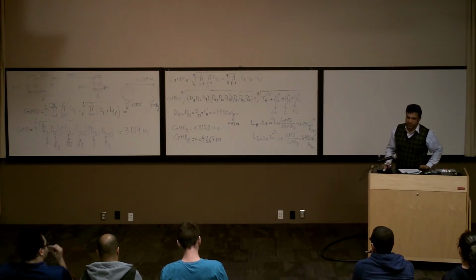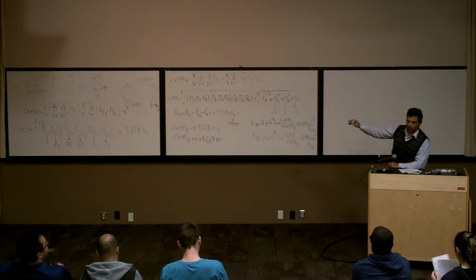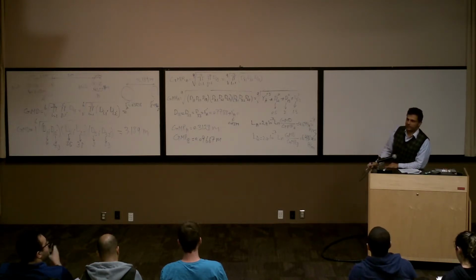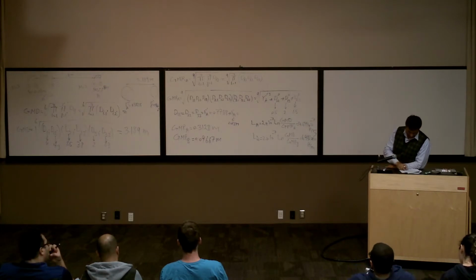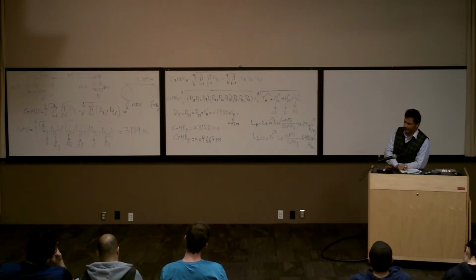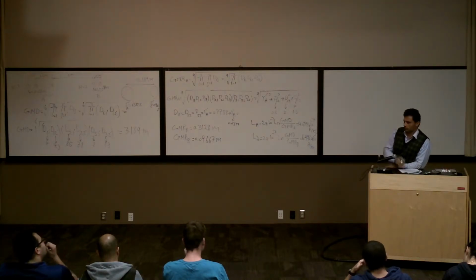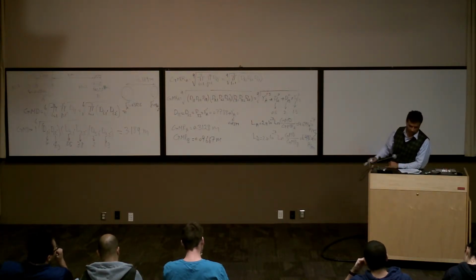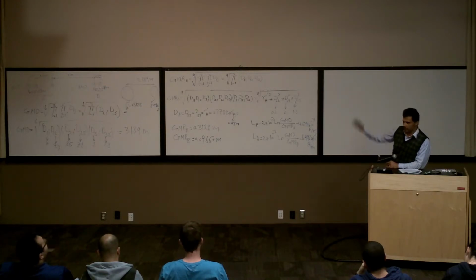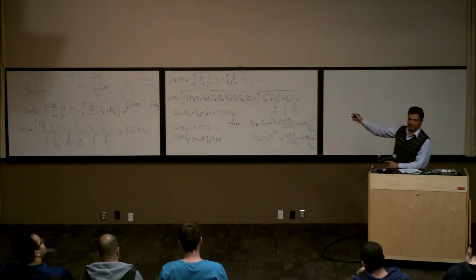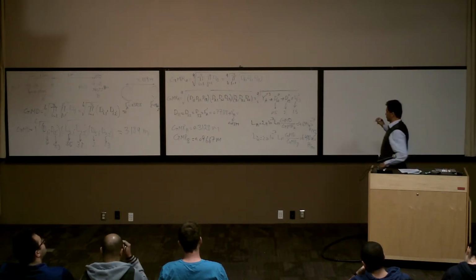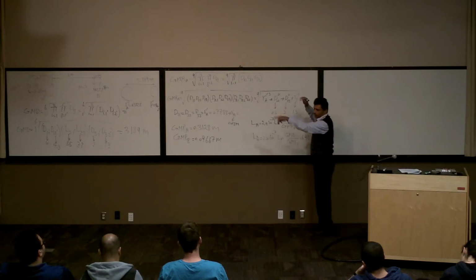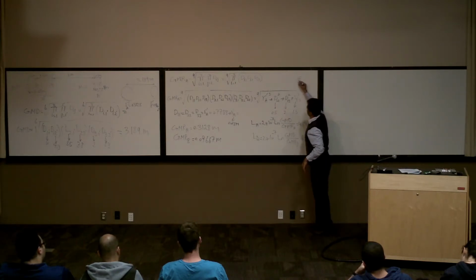But usually the GMR for all the conductors is given. If you look at your book in the appendix, there is a table A3 and table A4. In the last session, after we finish the capacitor, I'll bring one slide and we'll look at that table. Usually GMR is given because usually conductors are like this. They are not like that one over there, but they are like this.